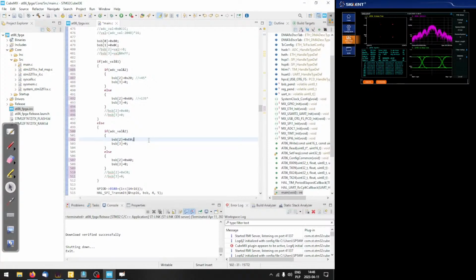But whatever, those values are not really relevant, and we don't care if the phase shift is positive or negative. So we just want the constellation to be filled with sample data points. So we've got 2, we need 4. Let's go ahead and add those 2. In our case, let's say that's minus 45 degrees, and this one is minus 135 degrees.